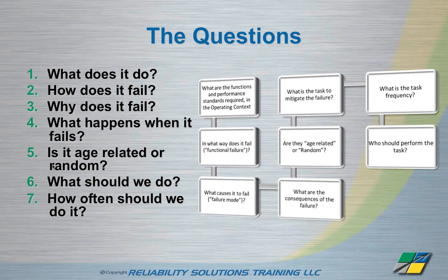The frequency that you should perform an inspection task is purely a function of what we call P to F, which is the point at which you can detect the failure and the time difference from that point to the time at which the functional failure occurs. In other words, it's how long it takes to go from a failure to a breakdown. And ideally you take that time and divide it by 2. But that is completely separate from criticality. So the mistake a lot of people make is they end up overlooking at machines. You have 4 different people going and looking at this machine, which is actually not necessary based upon the